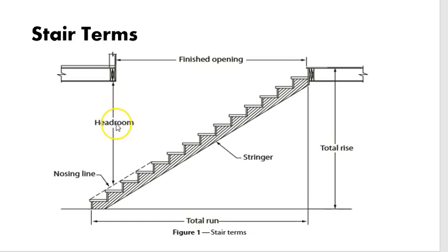There's a millimeter conversion that's close to that, 1950, I believe. That would be for private dwellings, and when we get into public, we need some more headroom there. It gets up to 6'8" for the requirement there. I think it's 2050 millimeters is the conversion. So that would be the headroom, and that's something we're going to use to calculate our finished opening of the stairwell.